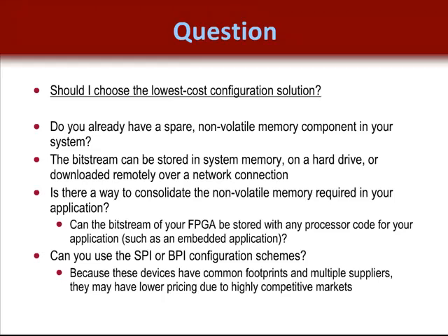If so, the compression or consolidation may allow you to purchase a smaller memory component and save some money. Likewise, can your bitstream be stored with your application code? Your software code, that is. If you're building an embedded design, then you should consider having your embedded application stored with your FPGA's bitstream in a single memory device. And we'll talk a bit more about some possible solutions that we offer in that realm as well.